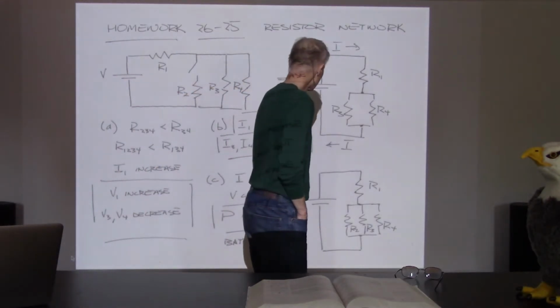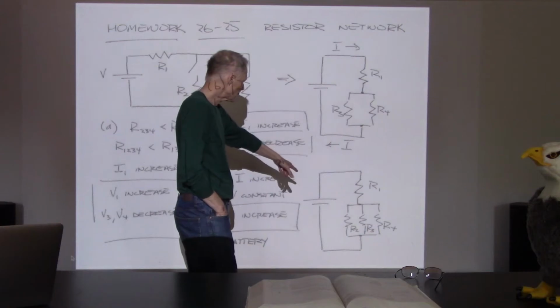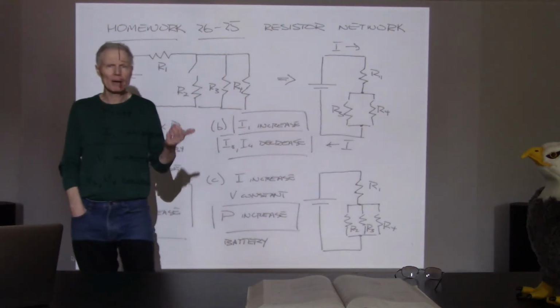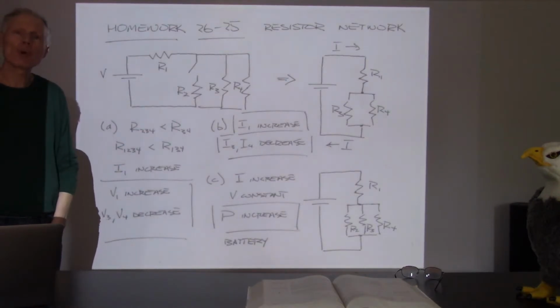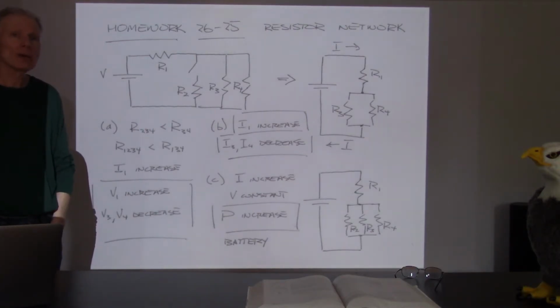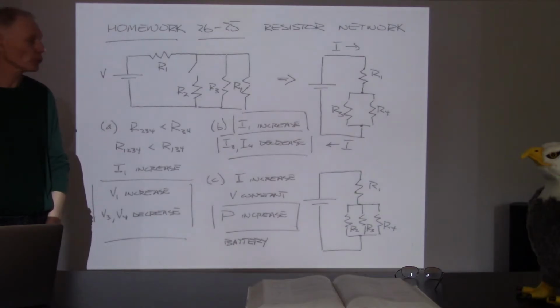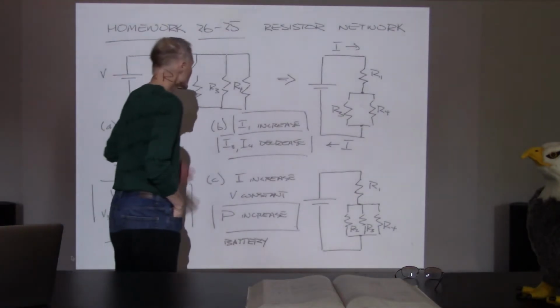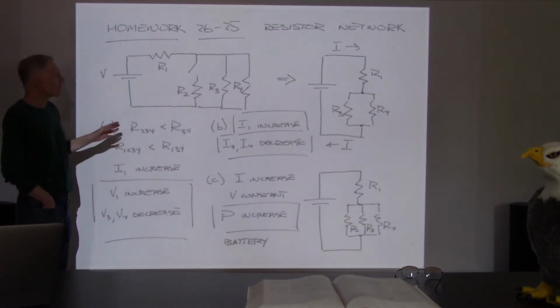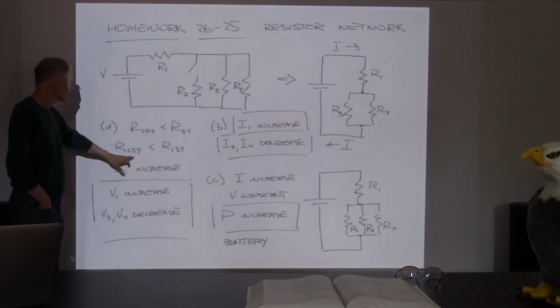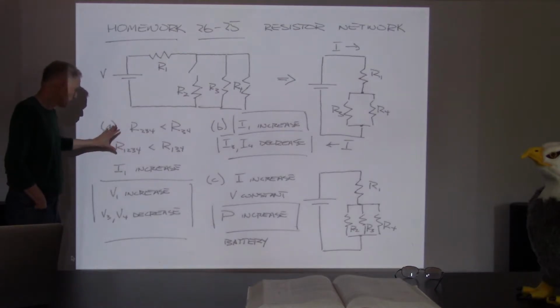So by adding that resistor in parallel at that one location, the resistance for the whole network is going to go down. And that doesn't matter what the values are for R1, R2, R3, and R4. It's independent. No matter what the values are for those 4 resistors, the overall resistance will decrease. And so it's good conceptual practice, thinking about what would happen in this case.